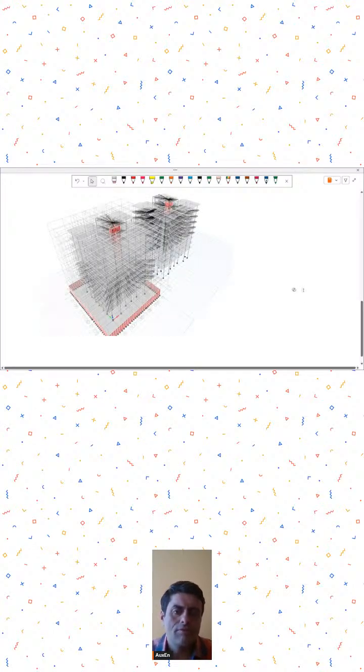Okay, so just for discussion purposes, I have brought this ETABS screenshot. What we have done is on the left side building tower, let's call it, we have assigned the D1 modifier, and on the right side tower, we have assigned the D2 modifier. Now what you can do is go to load patterns in ETABS, go for user loads, and once you go to user loads, you will see those diaphragm options available with the nomenclature also.